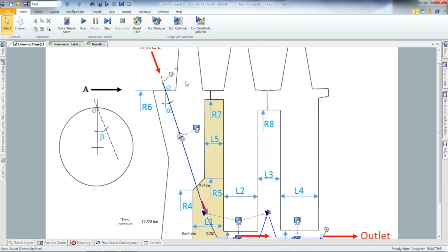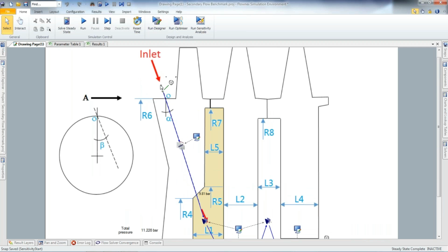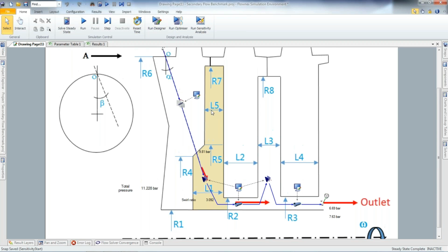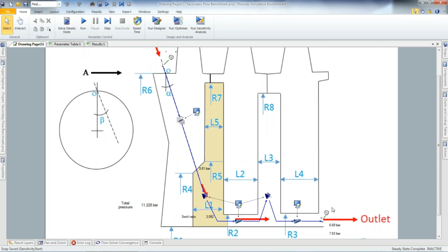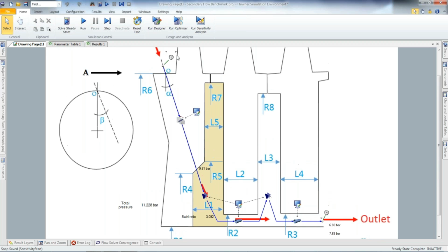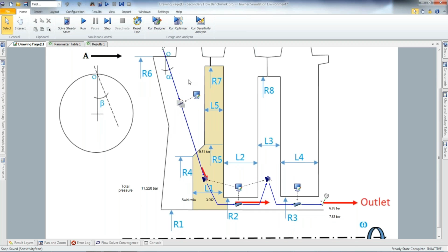So when it came to modeling this, it was simply just adding boundary conditions for our inlets and outlets. In this scenario, the goal was to calculate the optimal angles for a given mass flow to achieve the lowest pressure drop through the system. So we were able to specify a mass flow boundary condition at our outlet, along with our inlet boundary conditions from our compressor extraction point.